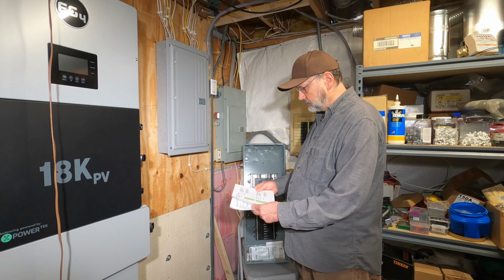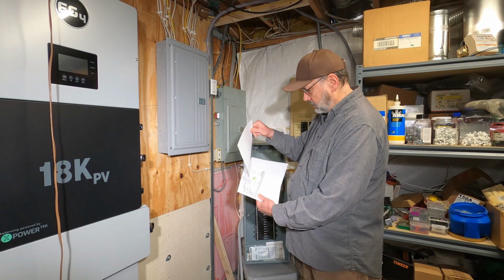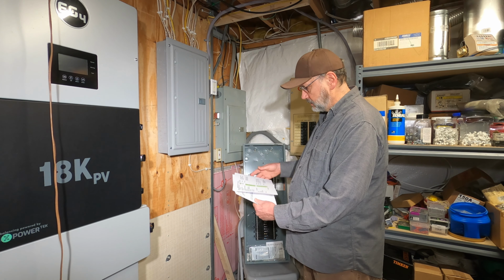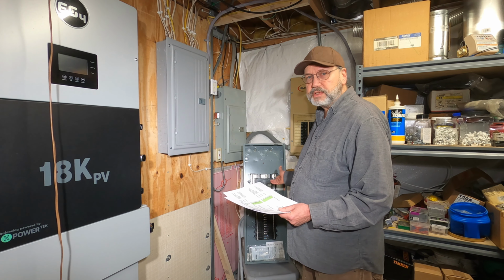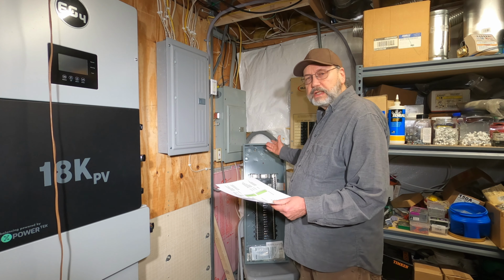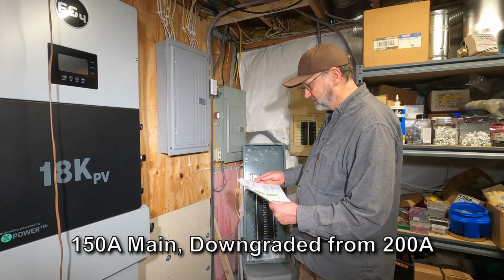The load I calculated on this is 85 amps. Theoretically, I could put a 100 amp panel in this house and it would be okay. But I'm going to have 150, so that should satisfy the inspector.